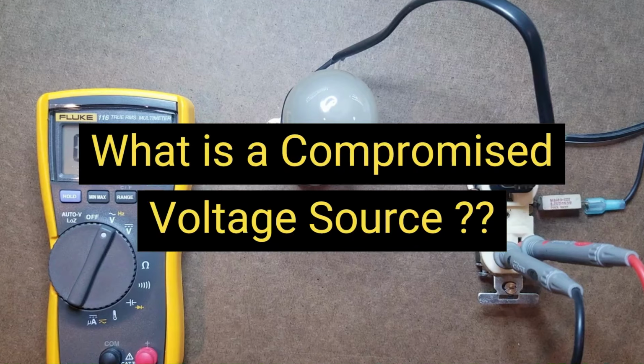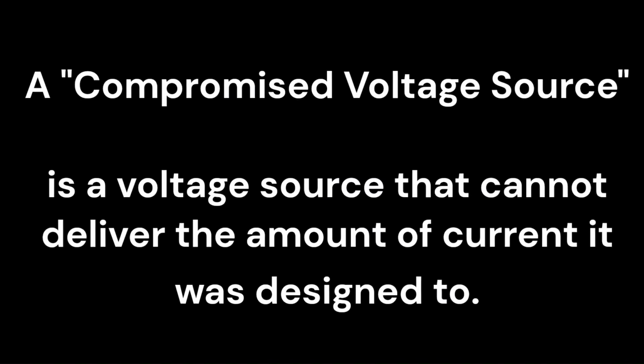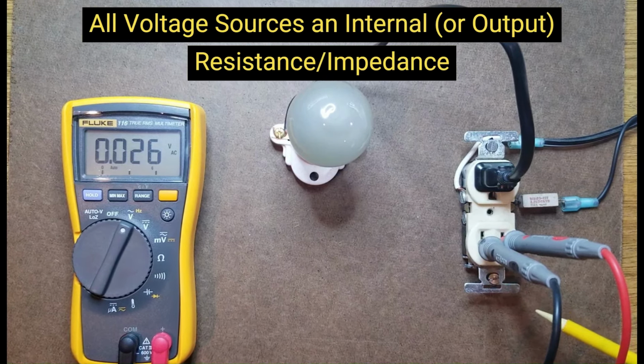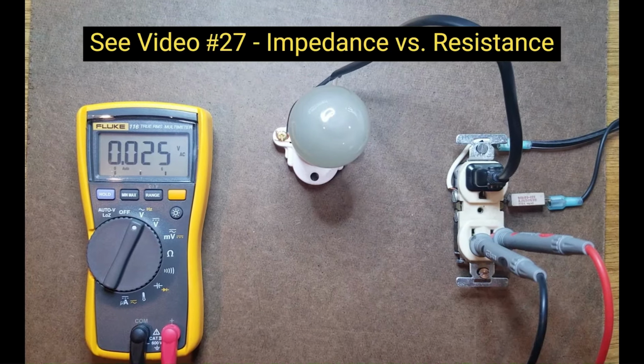But what exactly is a compromised voltage source? It is one that cannot deliver the amount of current it was designed to. All voltage sources have internal resistance, also known as their output resistance. Although the term impedance is normally used with AC current, let's keep it simple.